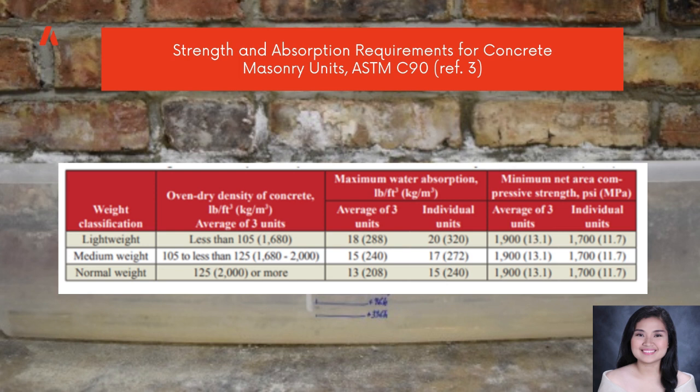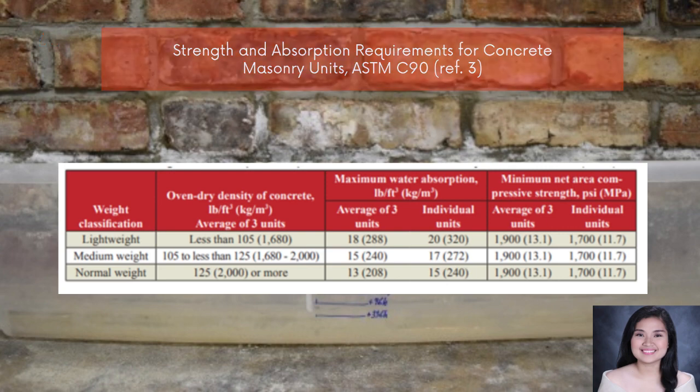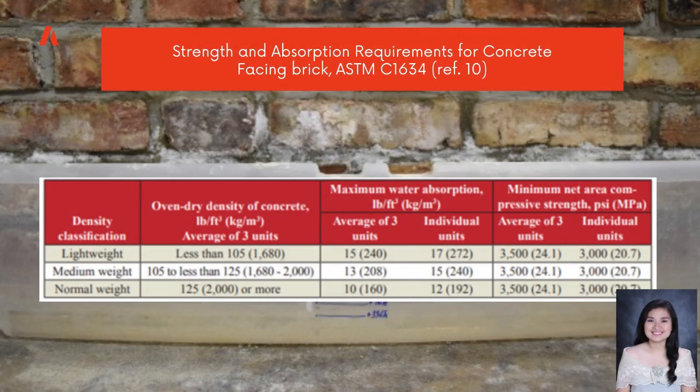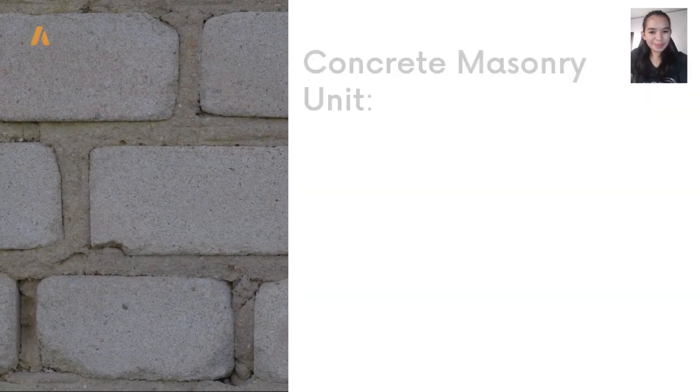Because concrete masonry units tend to contract as they dry, C90 limits their potential drying shrinkage to 0.65% measured using ASTM C426. Dimensional tolerances and finish and appearance requirements are similar to those in C90, with the exception that chip size is limited to 13 mm.